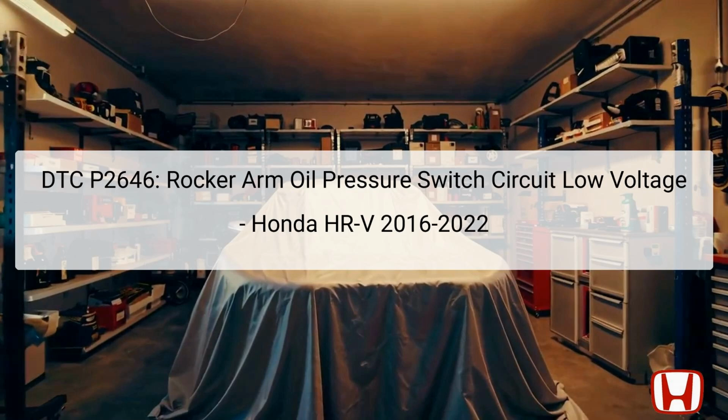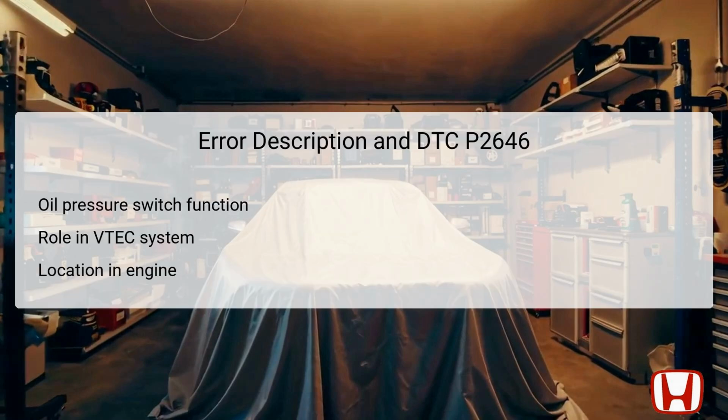or replacements. Error DTC P2646 defines a low voltage condition in the rocker arm oil pressure switch circuit, impacting the VTEC system's operation. The rocker arm oil pressure switch serves as an electronic valve controller, regulating oil pressure to critical components in the engine for enhanced performance.